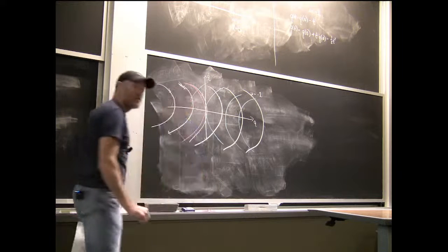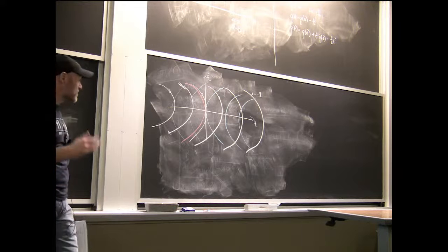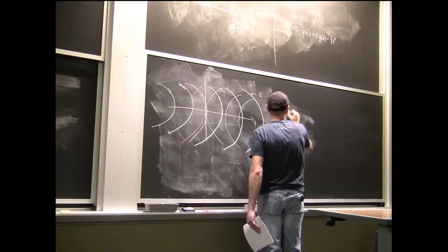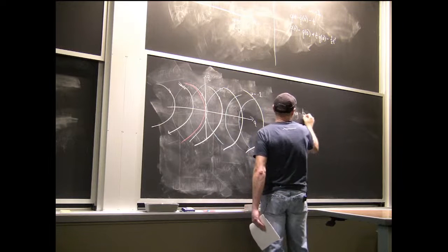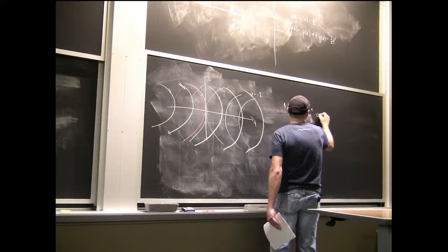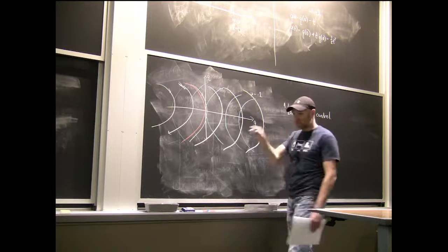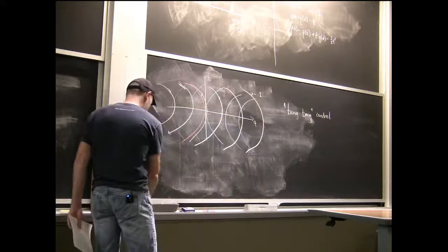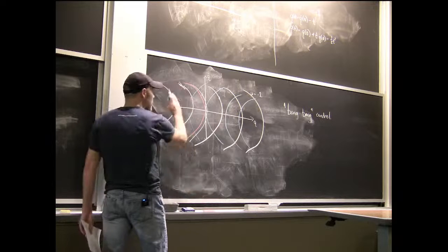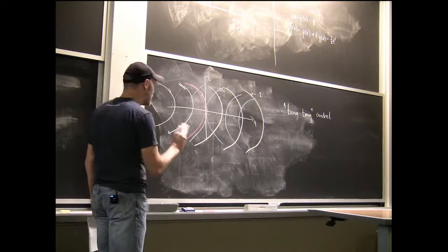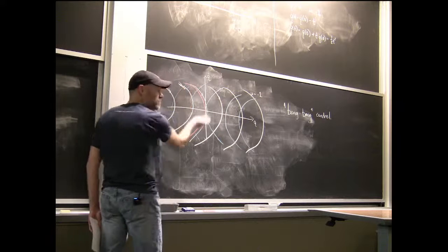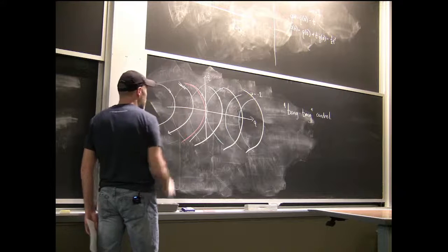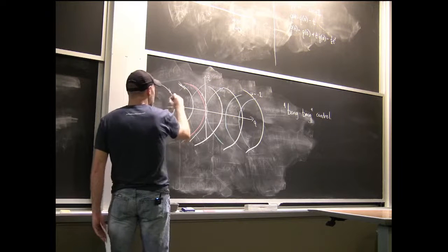Okay, so the optimal strategy, which is this, it's called bang-bang control, this idea of hitting the accelerator where you use your maximum acceleration until you use your minimum acceleration. That's a bang-bang controller. The recipe, now that we understand the possible solution curves, if we only have to think about the solution curves when u is either +1 or -1, then if I'm at some initial condition here, anywhere, I could pick any initial condition here.